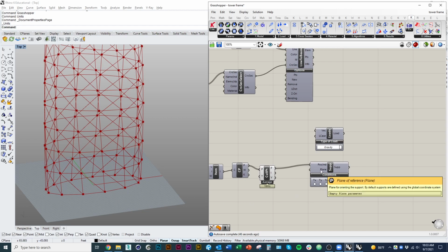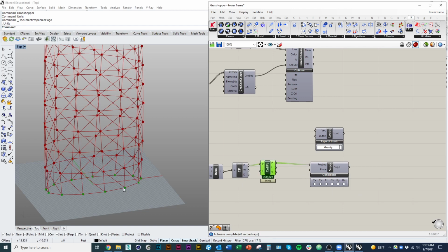And that's why we want to be able to set a plane, right? For example, if we had pin connections that followed the orientation of our curve there, we would have to set an individual plane for each of those to get that rotation direction right. In our case, we're just going to leave this empty because we don't have any special conditions. We'll just constrain everything.